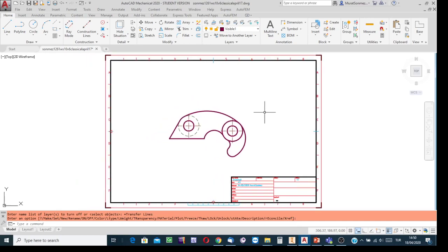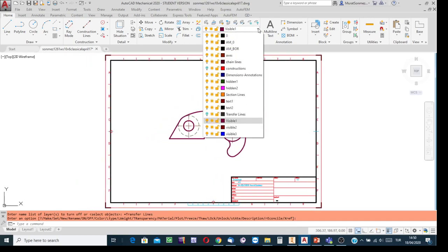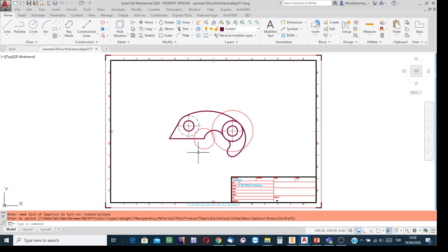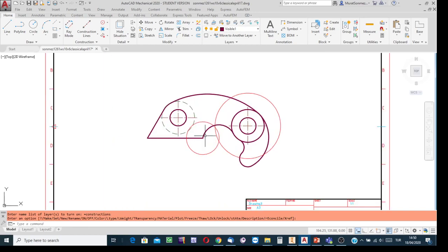Yes, that is the classical method, and in the classical method the difficulty is, as I said, without drawing this construction and that construction line, it is impossible to create this circle arc. It has only one tangent point, and for creating this straight line, we have tricks: tangency configuration, add symbol, and then clicking on the angle key, and then writing the inclination angle relative to a line it passes through the tangent point as measured in the counterclockwise direction. These are the tricky things to know.